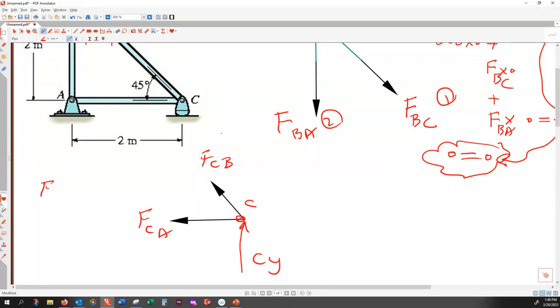So this free body diagram, is it concurrent or non-concurrent? Can you say that this free body diagram has only two useful conditions? It is concurrent. Why? Because all forces are colliding at C. So if I write net rotation with respect to C equal to 0, the result is 0 equals 0. Nonsense. That is not useful. Everyone agrees with that?